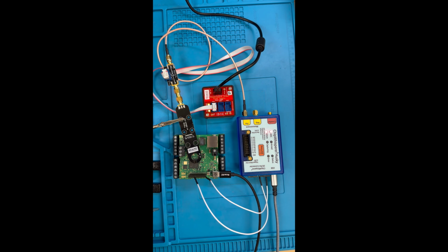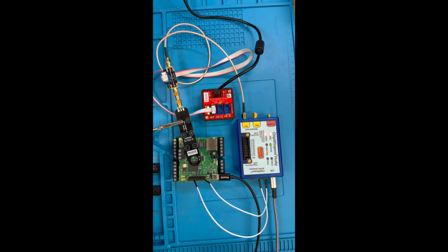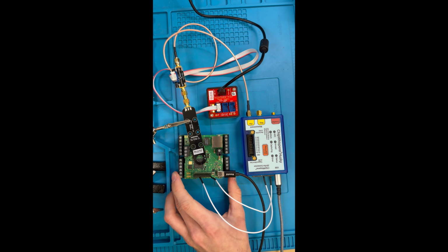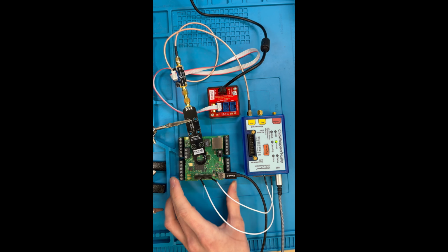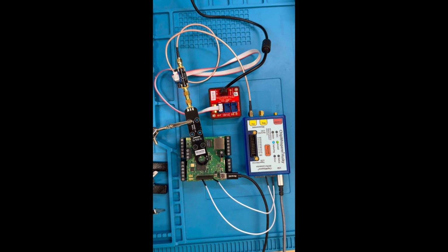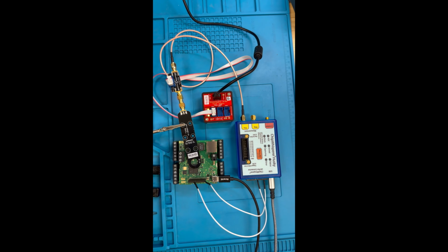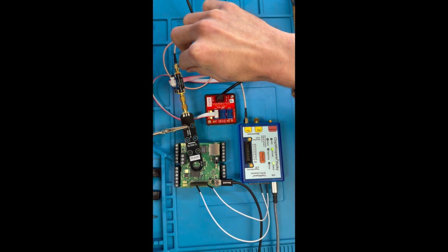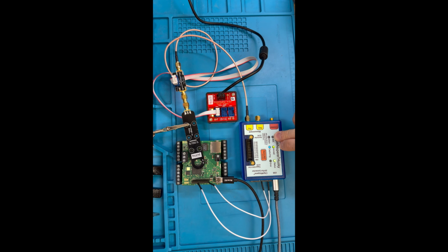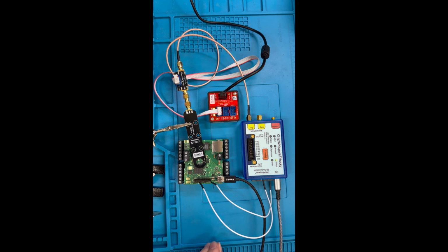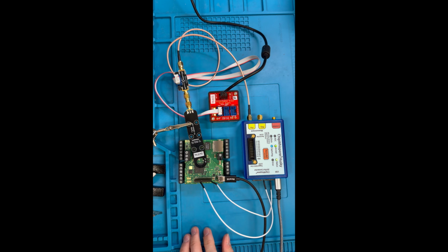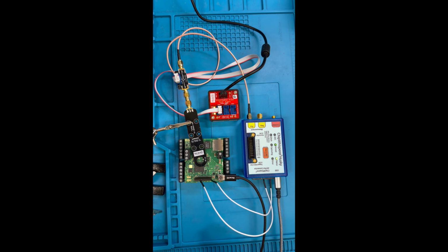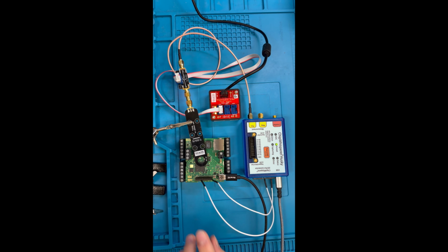So here's a look at our hardware setup. What we have is the Arduino Opta pulled out of the case and also with the top board removed to allow us access to these pins. We have our ChipWhisperer EM probe coming through a low noise amplifier and into the ChipWhisperer Husky. And for these pins, we repurpose an LED pin to serve as an AES trigger signal. So that's this wire coming out, and then this is a ground.